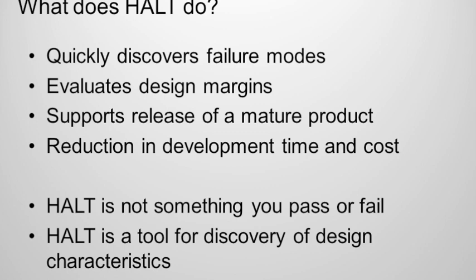So HALT helps the development process by quickly discovering failure modes. It evaluates design margins. It helps support the release of a mature product because you've had an opportunity to see a wide set of failure modes, and they've probably driven some corrective action and design changes. And if done early enough, are effectively free changes. This can dramatically reduce development time. And again, you don't want to pass or fail it. It's a discovery tool. We really should talk about it as a discovery tool. That's the correct frame and not just simply a test.